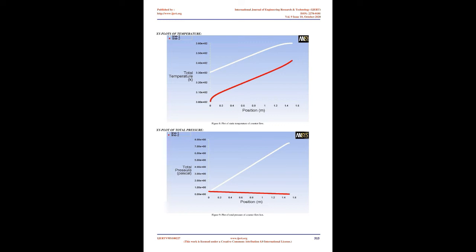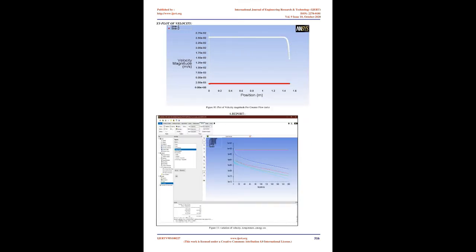4.2. Mesh. Initially a relatively coarse mesh is generated. This mesh contains mixed cells, tetrahedral and hexahedral, having both triangular and quadrilateral faces at the boundaries. Care is taken to use structured hexahedral cells as much as possible. It is meant to reduce numerical diffusion as much as possible by structuring the mesh in a good manner, particularly near the wall region. Later on, a fine mesh is generated.